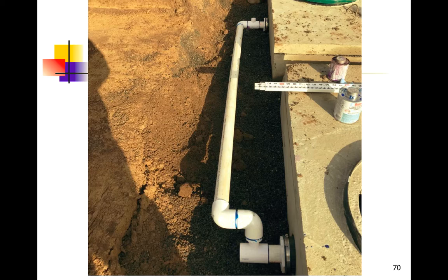Now, it doesn't matter if you're 2 or 3 feet away from the tanks like this installation, or you're 50 feet away. You need to have that minimum of 2-inch elevation difference between that tank adapter stub and the bottom of the basin, or what the excavation is for the basin. It can be higher, but it can't be any lower.